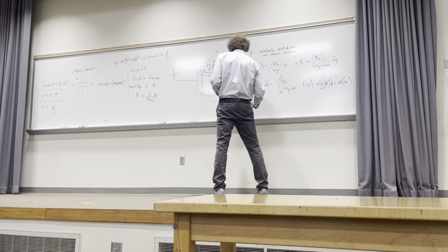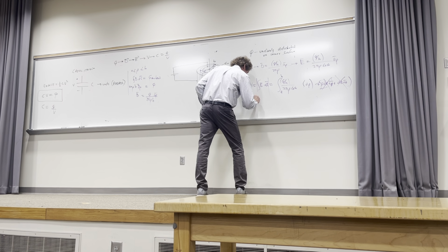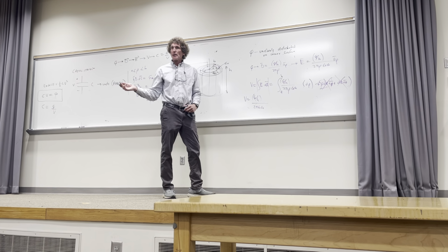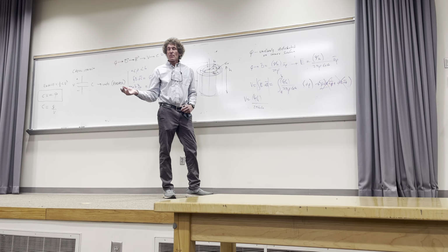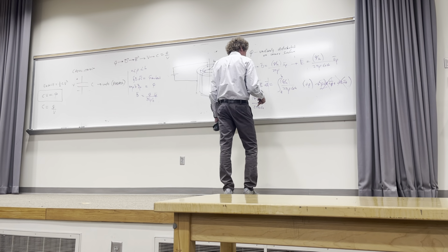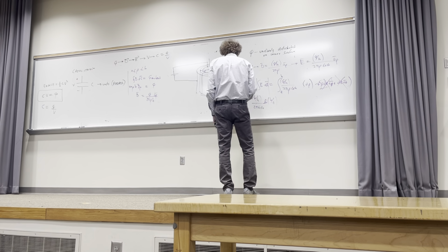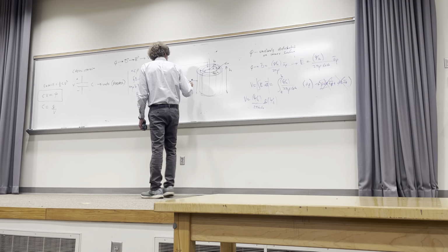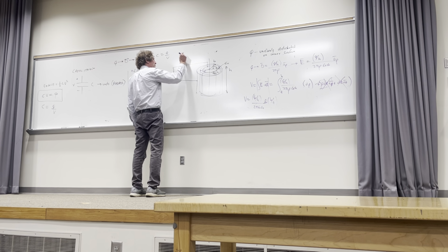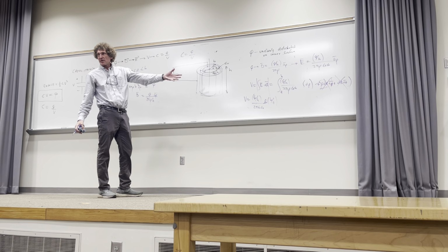All right, so what is that going to be? V equals what? I have Q over H over 2 pi epsilon relative epsilon naught. What's the integral of 1 over rho d rho? People? No. Natural log, right? Not log base 10, natural log of rho, but it's evaluated from A to B, or it's natural log of B over A. So that's the voltage. And therefore, for this system, what is the capacitance? I'll put it up here. Well, it's Q over V, or you can see really, I invert that and get rid of Q, don't I, class?